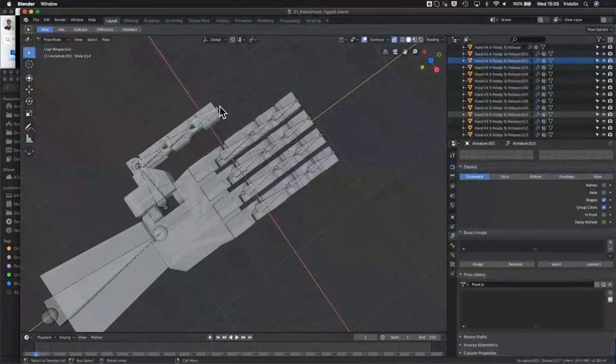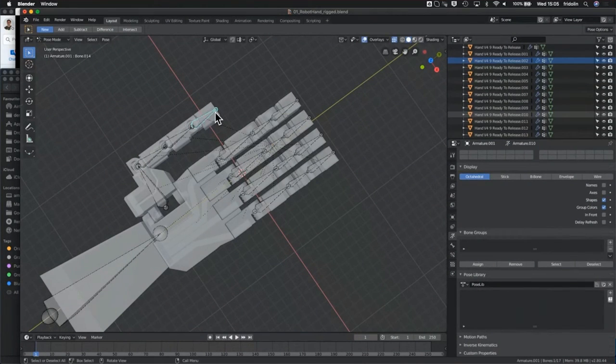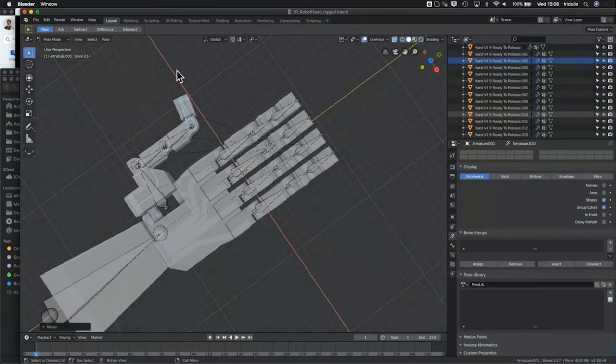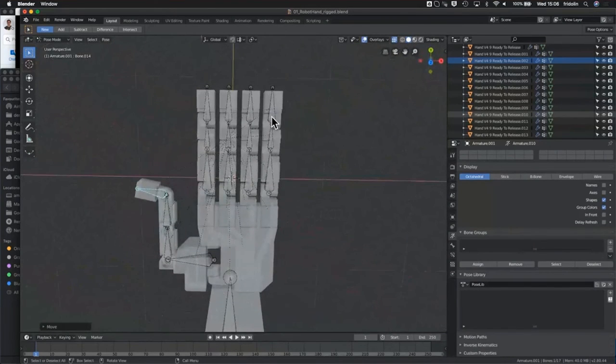If we take a fingertip and move that, there's no bone after it. So I select a bone, and then I press G, and now it's moving. And remember, we can left-click to confirm, or we can right-click to release it. So that's working with armatures and bones.